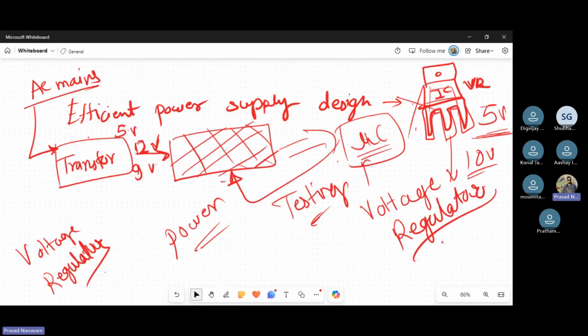Okay, and there are buck converters. Okay, so these are more efficient than linear regulators when stepping down from higher voltage to lower. Okay, there's power gating also, so implementing the power gating to isolate and shut down power to certain sections of circuit when not needed. That can also be done in the power gating.